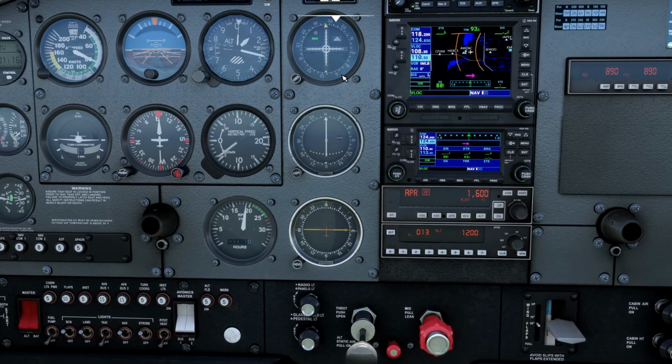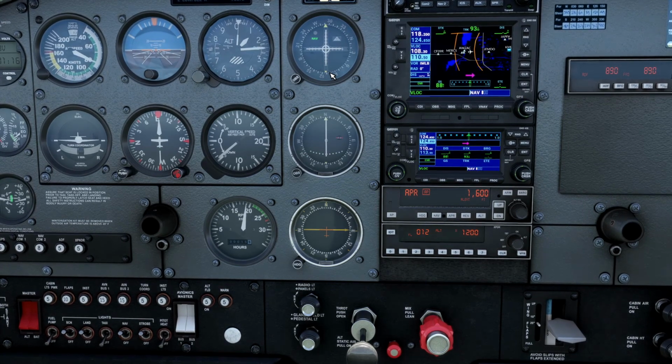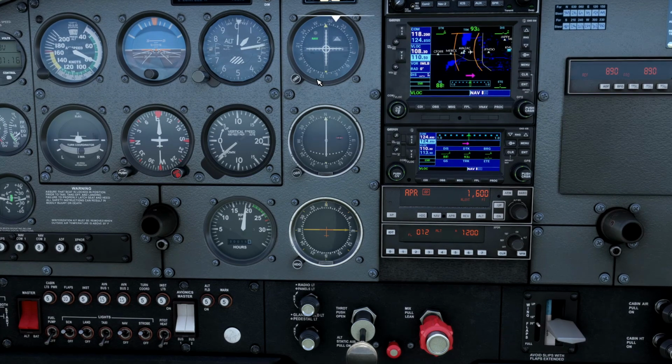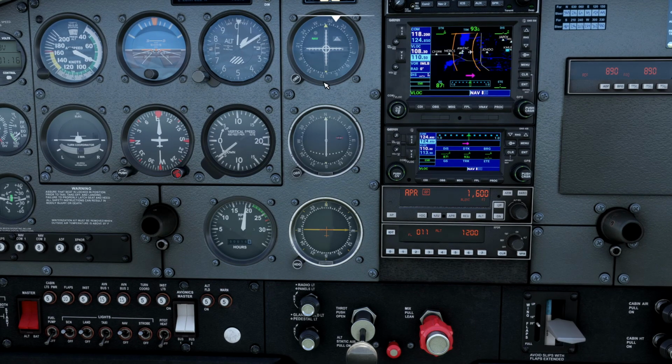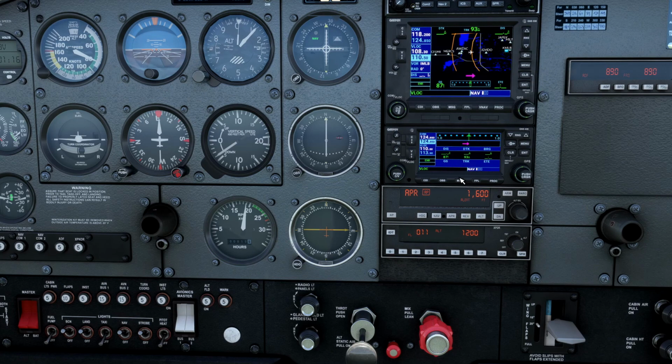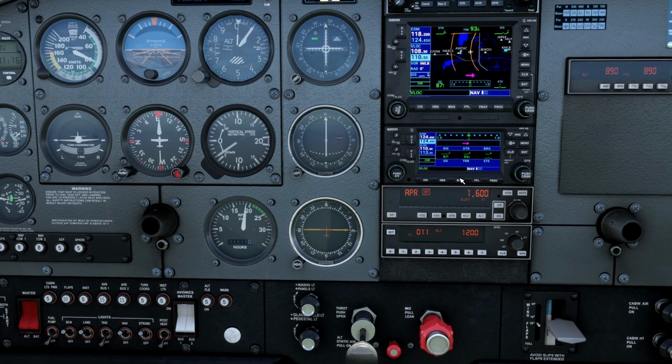If you do leave it on all the way to the ground, it's not going to flare. It's going to go into the runway at about 300 or 400 feet per minute, and it's going to do it at a flat attitude. So you'll potentially end up with a flat landing and potentially a hard landing, so it's not a good technique. The best technique for executing a missed approach, especially near decision height on an ILS with the autopilot, is just to turn the autopilot off and fly at least to a reasonable altitude.